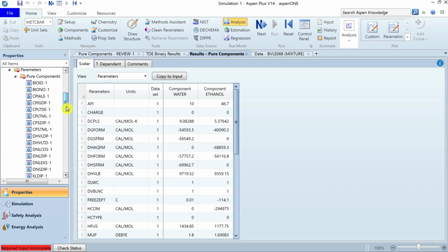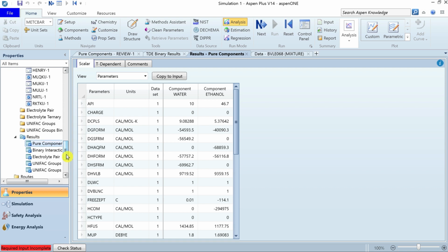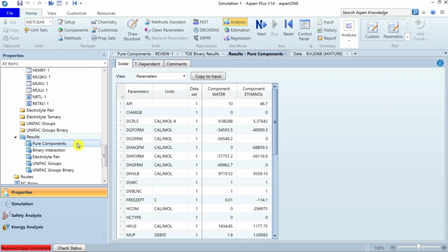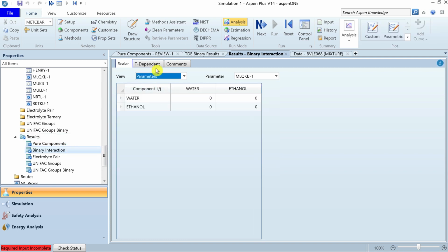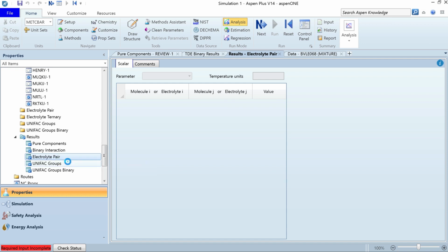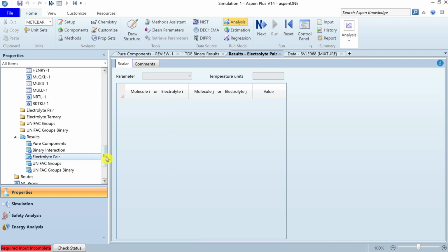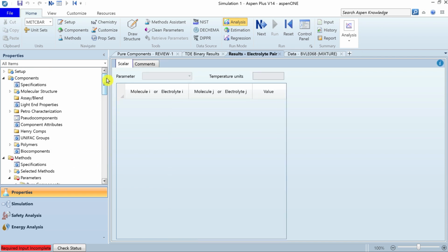You can notice a couple of other property parameters have been added to the pure component property section that were not present in the case of the property retrieval using the review option. Now the property information includes the retrieved information for the pure components as well as binary interaction parameters, specifically the temperature interaction parameters for the corresponding property model. So this is how you can use three different ways to retrieve the experimental property and property parameters of the pure components and multi-component mixtures.